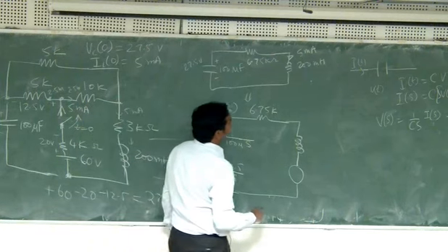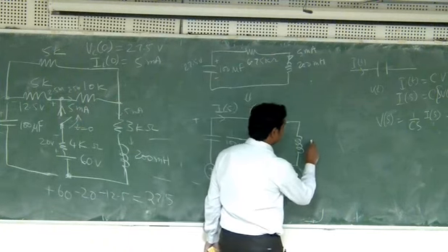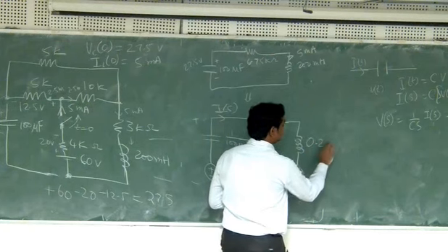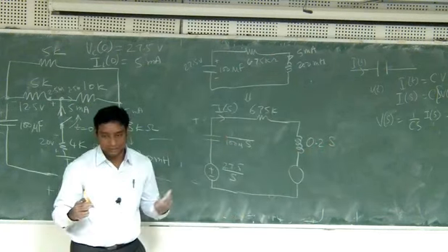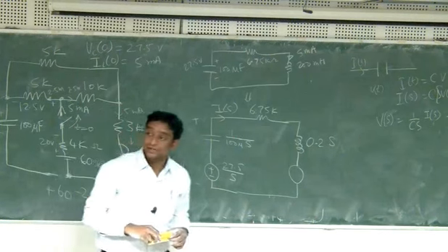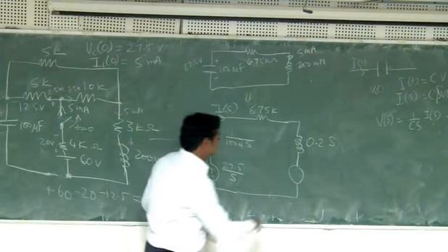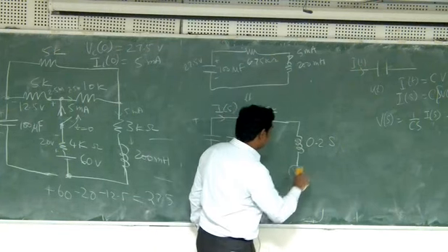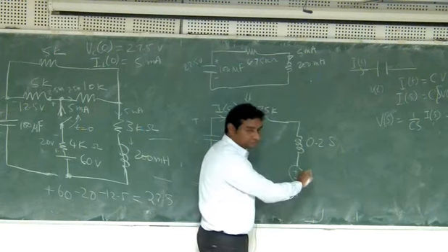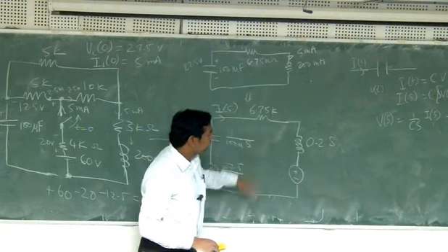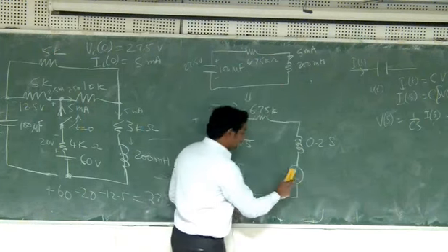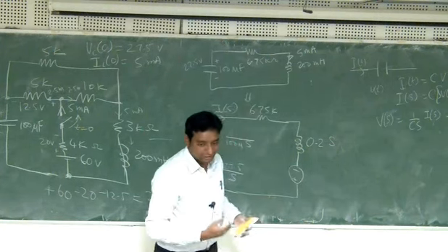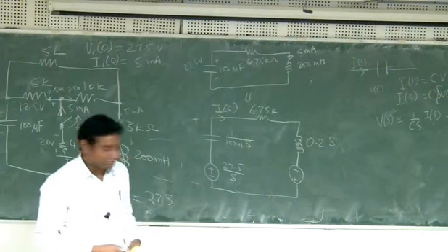So this is 200, that means S into 200 milli, or I will write it 0.2 S. Okay, S into L. We still have some time. So this is plus minus, okay, or is it? Because the current was going down, it will try to continue in that same direction. Therefore, the voltage induced will be something like this.